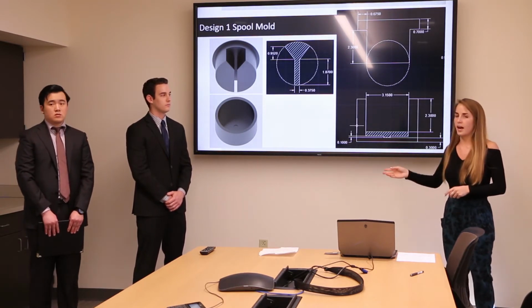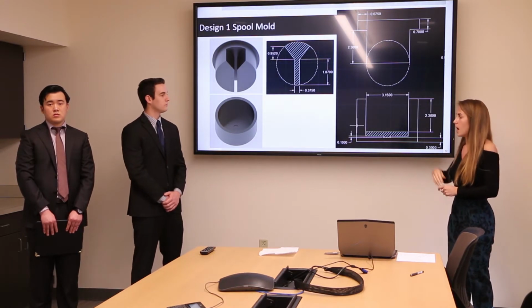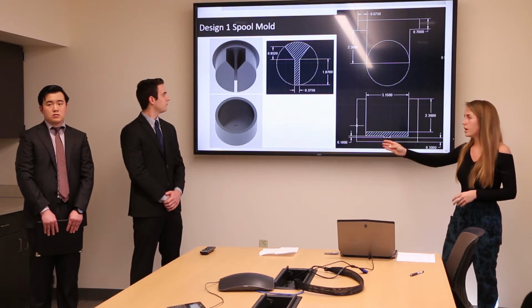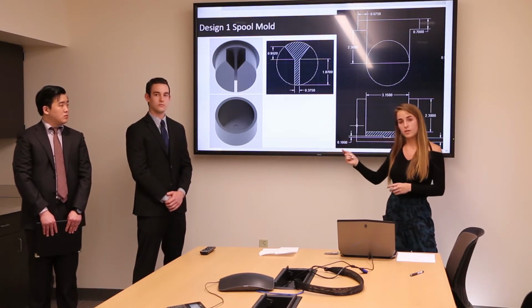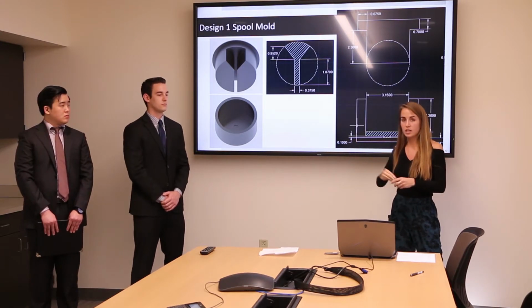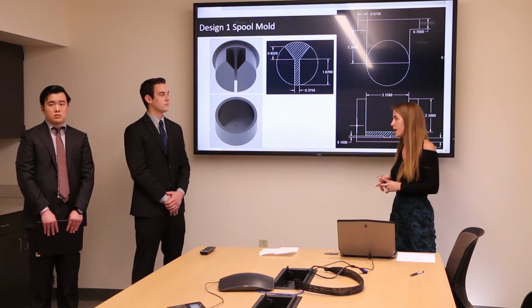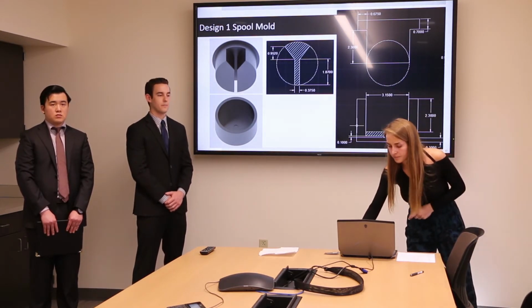Really quick to discuss, Kyle's going to go into it more in detail later, but really quick to discuss how we are going to machine this. He'll talk about it, but just as the visual is up on the board, for this side B mold, we're going to take the 2-inch diameter drill that we use for the portholes and initially clear out the cavity and then mill out the rest, which will save us a lot of machining time. Kyle again will discuss that later, but I just wanted to mention that here.